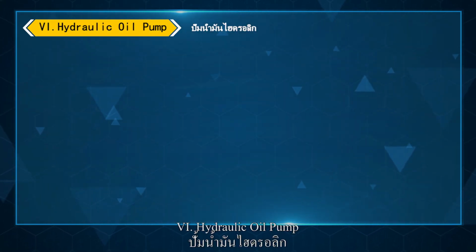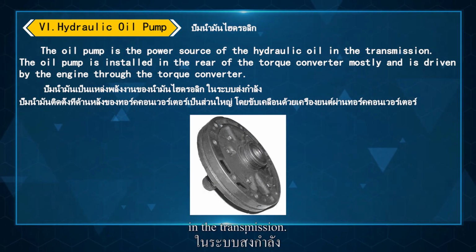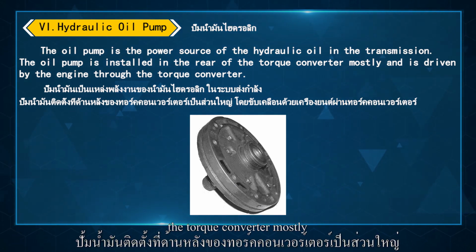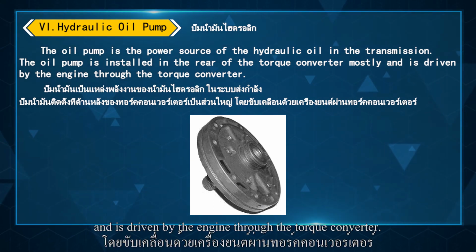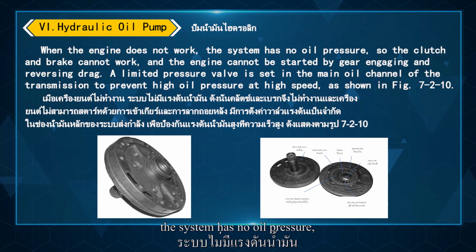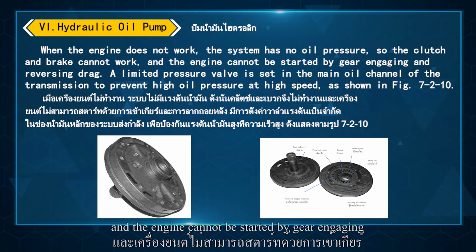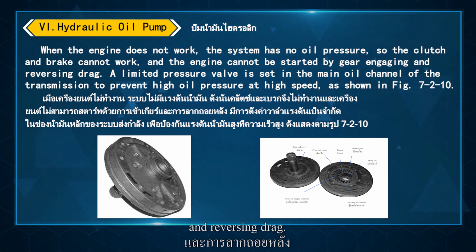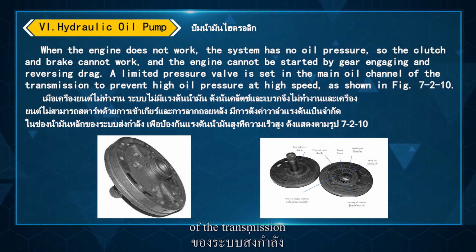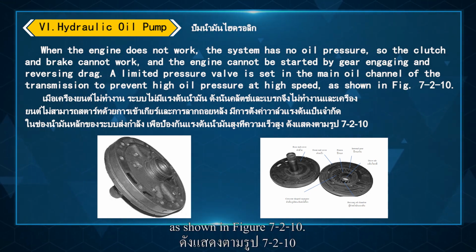6. Hydraulic oil pump. The oil pump is the power source of the hydraulic oil in the transmission. The oil pump is installed in the rear of the torque converter mostly, and is driven by the engine through the torque converter. When the engine does not work, the system has no oil pressure, so the clutch and brake cannot work, and the engine cannot be started by gear engaging and reversing drag. A limited pressure valve is set in the main oil channel of the transmission to prevent high oil pressure at high speed, as shown in figure 7-10.